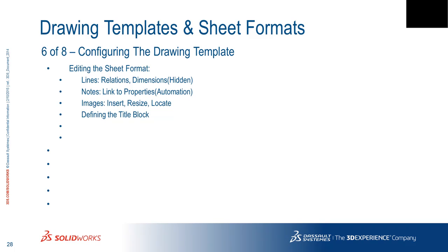If the sheet is just documented at the same scale, fine, but if you've got multiple sheets, then you're really in trouble. The Save As option should have that scale 1-to-1 box, and I haven't ever had any drawings go out that weren't one-to-one. You had to go sheet by sheet. You couldn't send them all out at the same time. Yeah, that does sound familiar. There should be a setting in the save, but as you said, you probably have to do it sheet by sheet to get the one-to-one scaling each time.